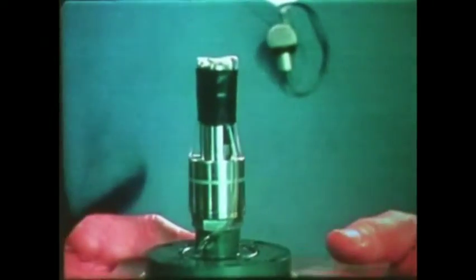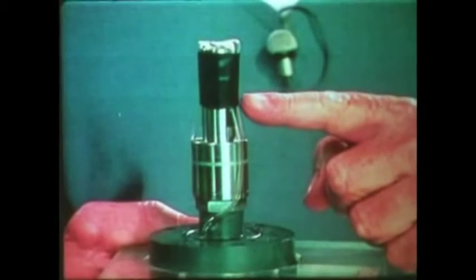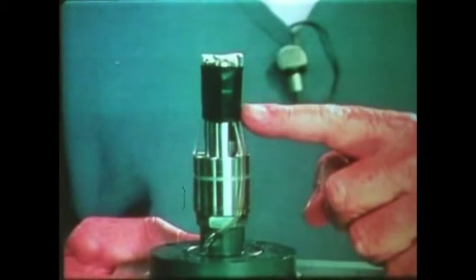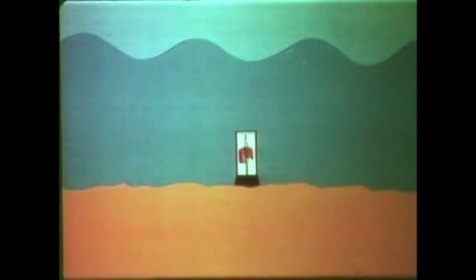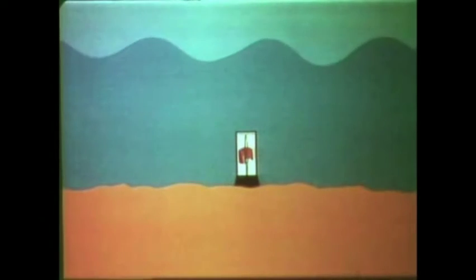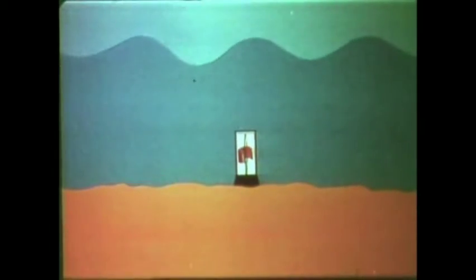This is it, and the key element is the Vibrotron transducer shown here. A thin tungsten wire is mounted in a cylinder between a rigid base and a diaphragm. The wire vibrates. As the water pressure increases under a wave crest, the diaphragm is depressed, the tension in the wire is slackened, and the frequency of vibration reduced. The wire oscillates in a magnetic field inducing a fluctuating current. This electrical signal is amplified, transmitted, and recorded.